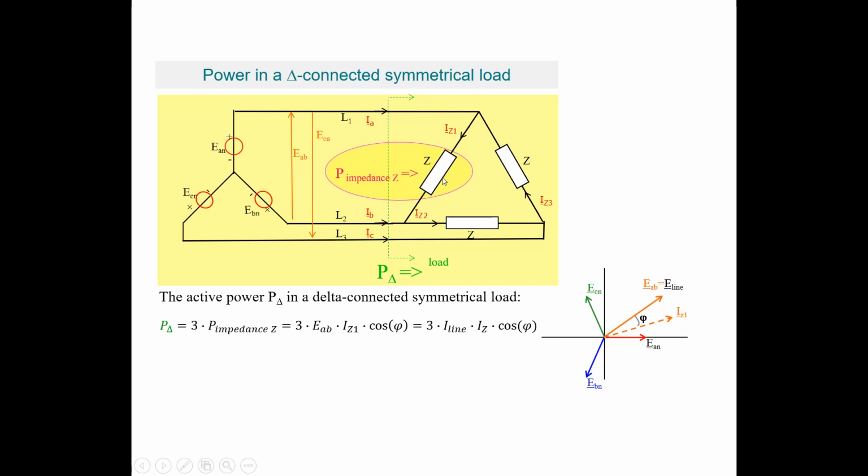Well, we have an expression about the total power with the line voltage over here, and we have that strange expression for the current through one of the impedances, IZ. So what we are doing now is we are going to express that current, IZ, into a line current defined here as IA. And what we have defined is also that the currents flowing out of one of the phases is positive when they are flowing out of the positive direction of the voltage source.